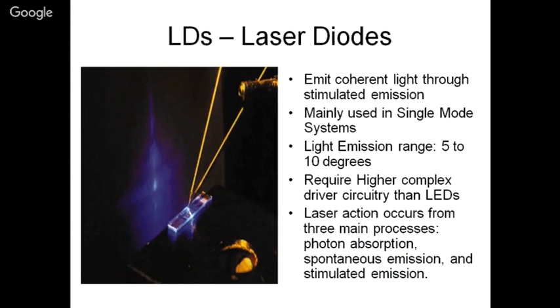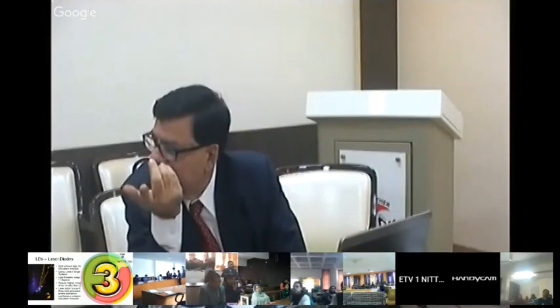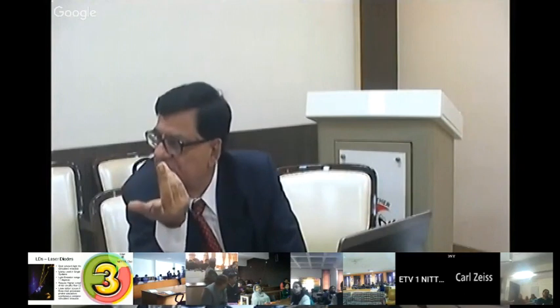Initially, a laser is an LED. Then when the current reaches a threshold, only then it lases. And we have to modulate light on a very steep curve. So lasers are suitable for digital communication, not for analog. Suitable means they can be used, but they are always used for digital communication. Whereas LED can be used for analog communication also. It can be used for digital also.